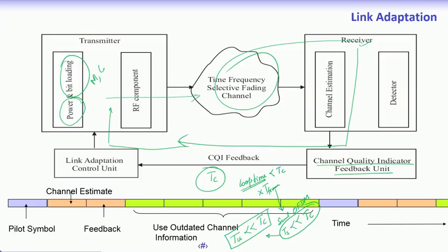So, we stop our discussion over here, and we will move on to other things for OFDM from this point. However, it is very important to remember whatever we have discussed, because this is the foundation based on which we will discuss several other things. The entire physical layer or even the entire communication protocol stands on this basic grid architecture. So, we must remember that there exists a bottom layer grid architecture on which all these things happen, and there is a frame structure. We will discuss the specific details of the frame structure of the 5th generation system at a certain point, but overall this is the skeleton on which the entire signal protocol stands.